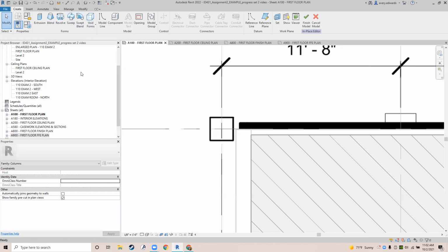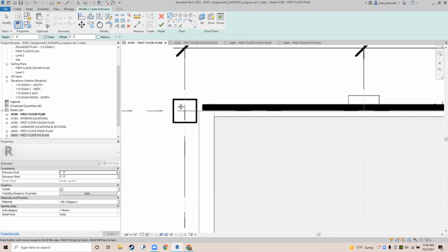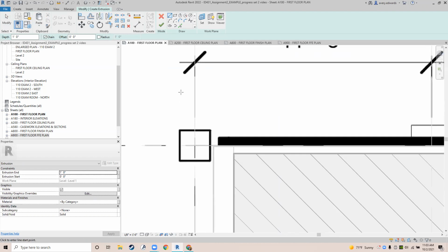The only things I ever use, even modeling more complex things, are extrusion and void forms. And really you can kind of get away with not having to use void forms either. You'll pretty much always click Extrusion, and it works just like modeling extrusions in Rhino or something else. Now we're ready to draw. We see our little drawing crosshairs and we've got this line selected. And I'm just going to draw the 2D shape that I'm going to extrude. So I'm going to click.